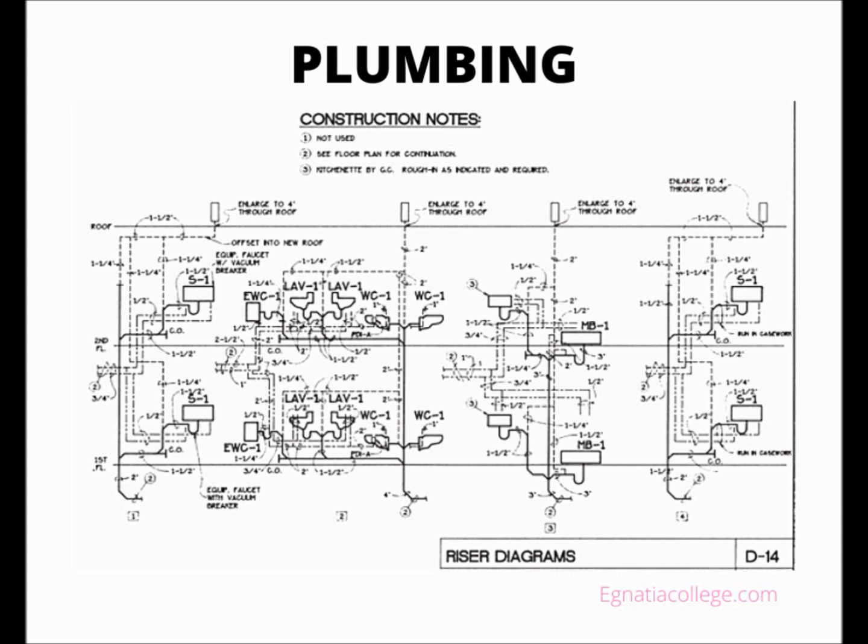Plumbing. The plumbing for the school addition consists of DWV (drainage, waste, and vent) piping to remove effluent, wastewater, hot and cold water distribution, and fixtures. The DWV system is more complex for a building this size than for a house, because the large flat roof collects quite a bit of water in a rainstorm and there must be a way to get rid of it. Therefore, the second floor plumbing plan shows roof drains, marked RD, and storm drain piping, indicated by a heavy line.